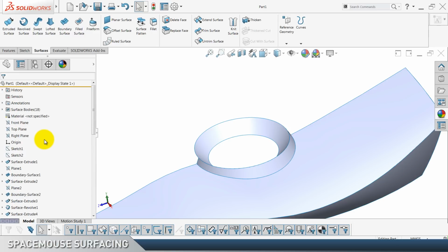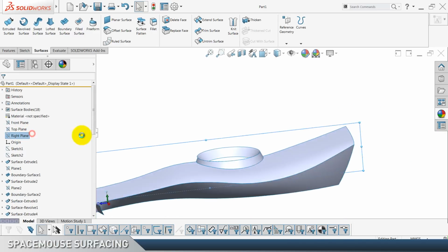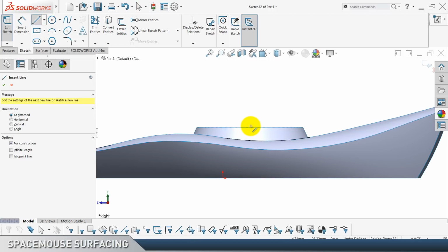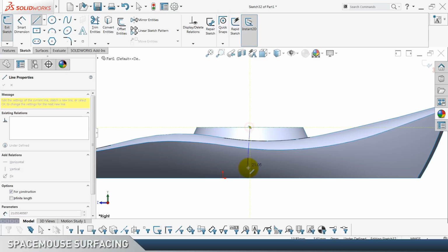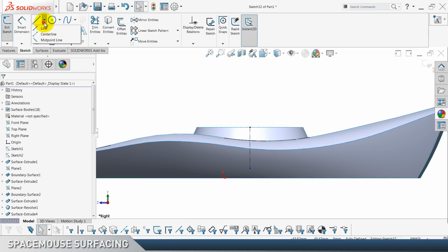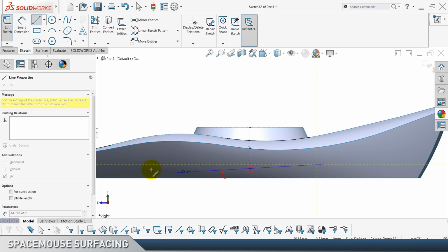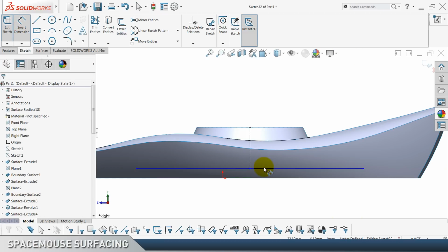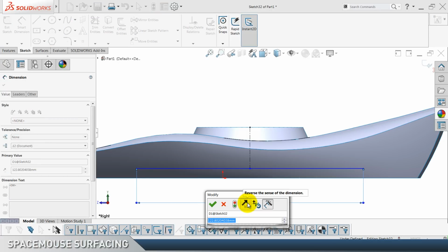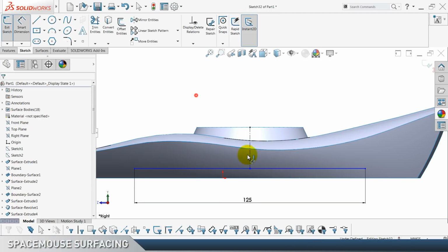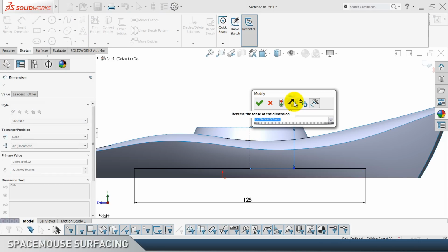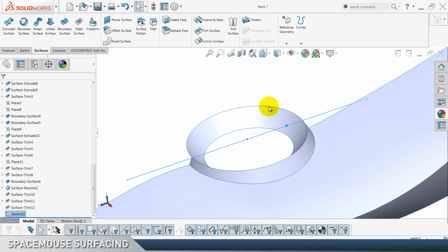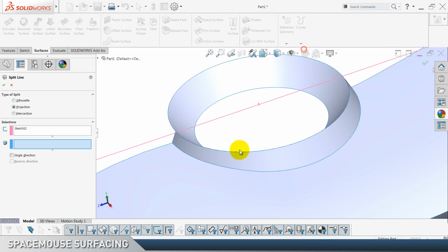and we need another split line, right plane sketch. It's gonna be something like a center line from the midpoint down. Make sure it's vertical, and the midpoint line, make sure it's horizontal, and make sure it's long, like longer than 120, and the length of this one is gonna be 0.5. Exit the sketch. We're gonna split this one,